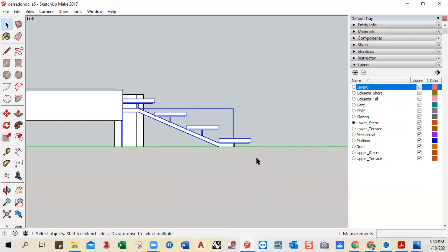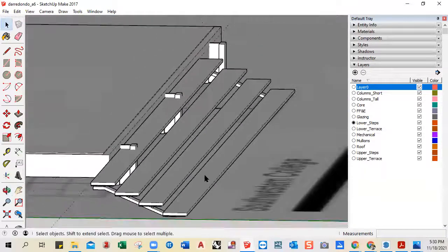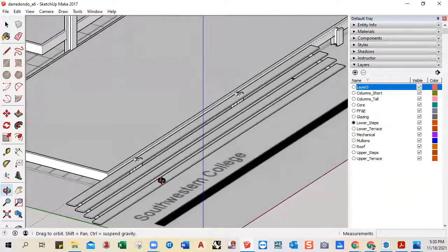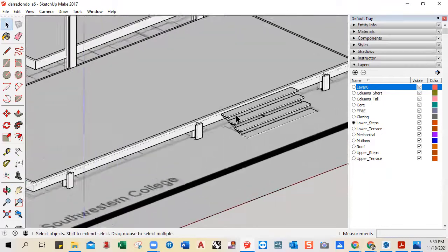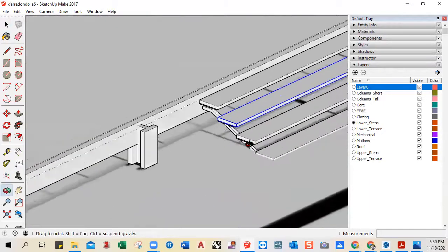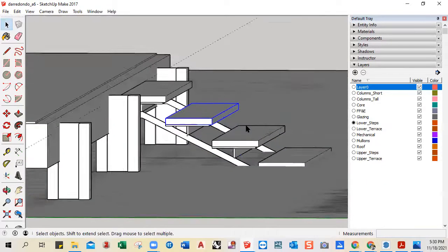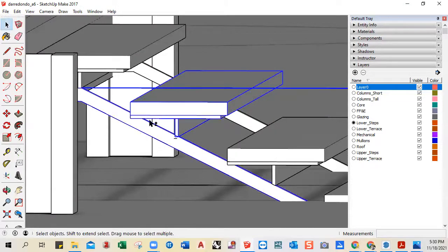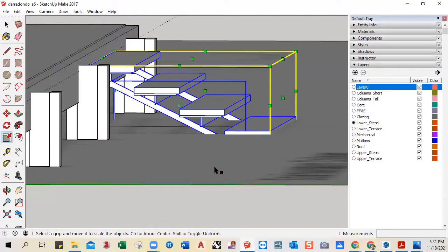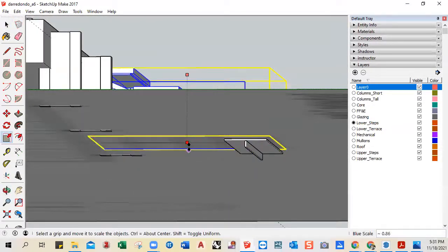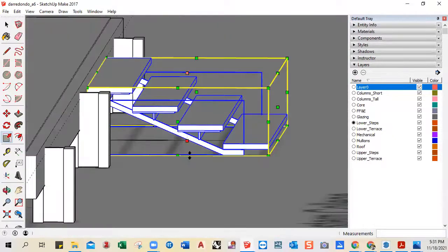So it's sitting properly. What's our dimension now? It's scaled in both directions. All right. That's why I don't like using side nodes and using center nodes instead. Let's try that one more time. Selecting here, holding down shift to select multiple. As for scale, this center node is the one I want. There you go. I should have just done that.